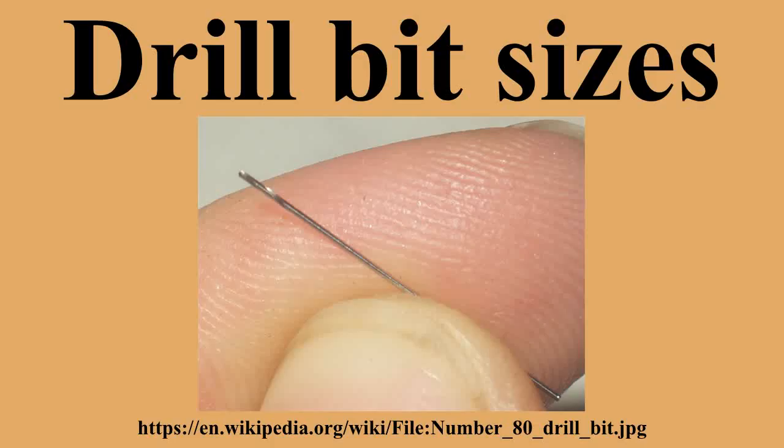Spotting drill bit sizes. Spotting drills are available in a relatively small range of sizes, both metric and imperial, as the purpose is to provide a precise spot for guiding a standard twist drill. Commonly available sizes are 1/8, 1/4, 3/8, 1/2, 5/8, 3/4, 4 mm, 6 mm, 8 mm, 10 mm, 12 mm, 14 mm, 16 mm and 18 mm. The drills are most ordinarily available with either 90 or 120 degree included angle points.